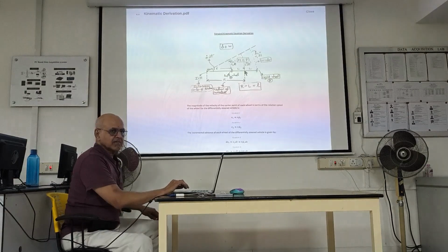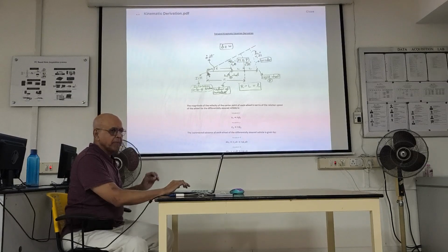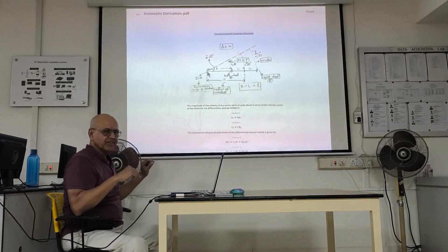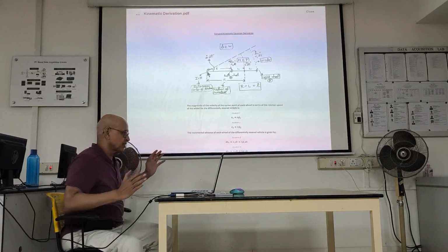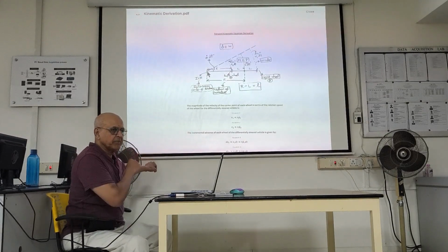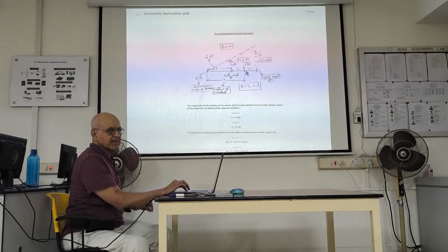Do you agree that if this vehicle is on a circle, there will be some center of rotation? Remember the circle program I gave you? There is a center of rotation. If it's going this way, it's somewhere out there. That point has to be in the middle of the circle. Therefore, the radius of the circle is the distance between that and the midpoint of the vehicle.